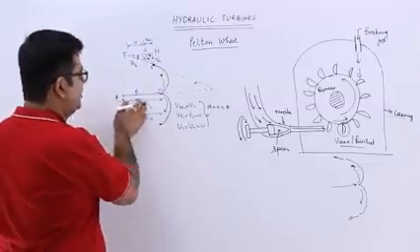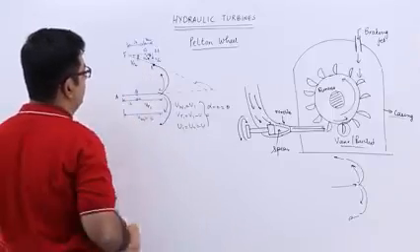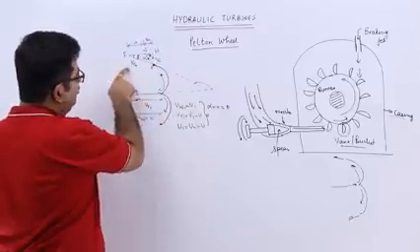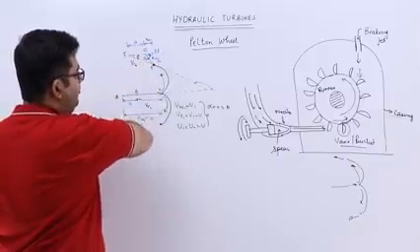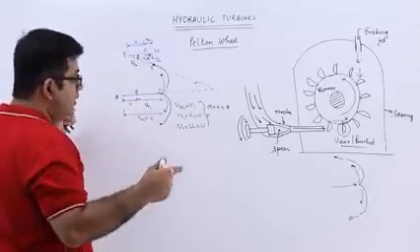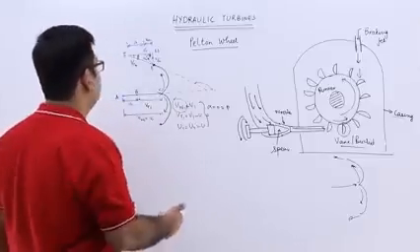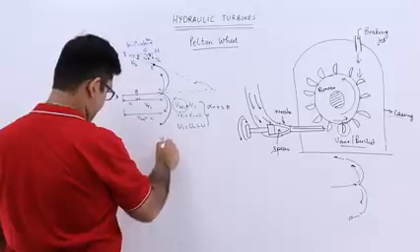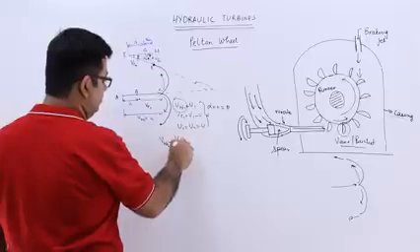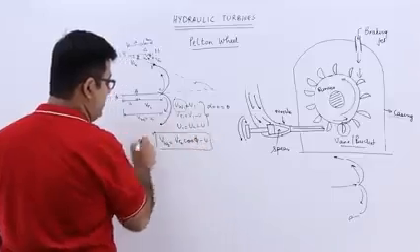So this is how it strikes and then splits up, and comes out from the tip at the outlet. This is how it moves out. So you have the OVT, again the similar thing. You have the VR2, you have V2, you have VF2, VW2 and U2. Okay, phi and beta. So I'm more interested in the VWs, because with the help of VWs I can find out the force exerted. Right, so let's find out VW2. This would be VR2 cos phi minus U2, or U simply.